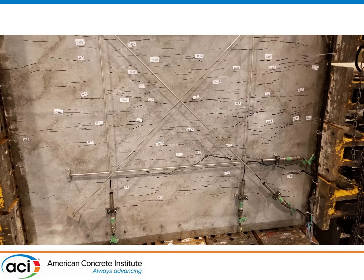At this point, you can see, though, it's cracked on the right-hand side, but not on the left. That's unusual. That's the fibers allowing that. That's not something normal concrete does. We'll see that did cause some interesting results from the instrumentation on the surface. But as the load went up further, the crack got wider until it opened up to about 20 millimeters, at which point we stopped the test. Very large shear strains, very good performance.